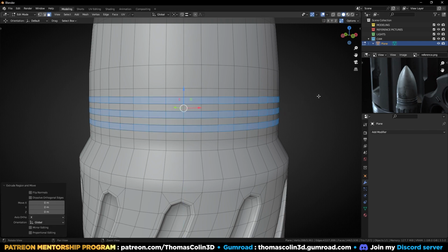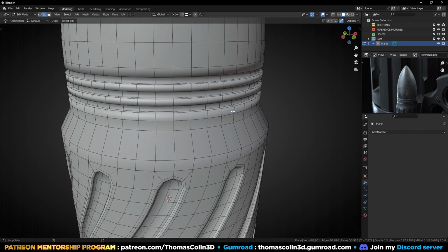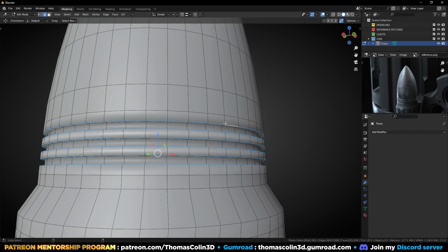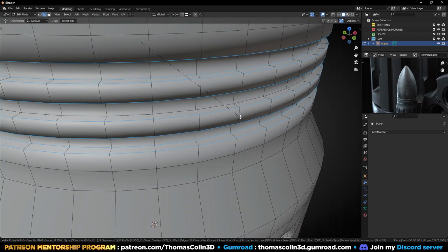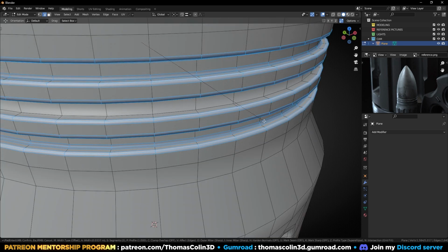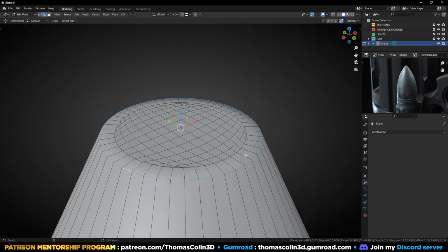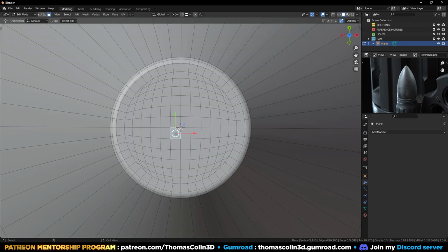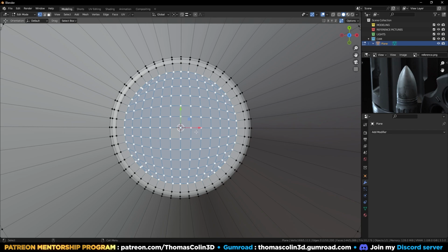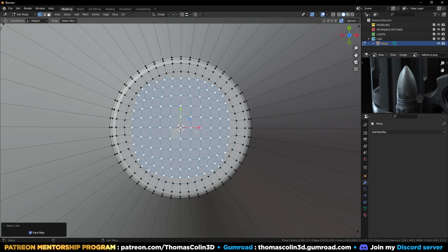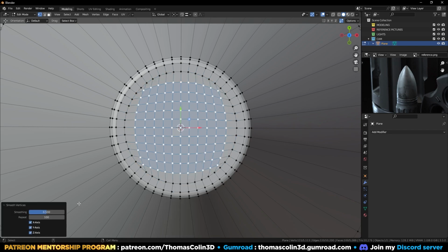E, right click, Alt S, select the sharp edges, Ctrl B to bevel with 1 segment, P to set the shape to 1, select this edge loop as well, Ctrl B, select one face, Shift G to open the Select Similar menu, select Coplanar, press Ctrl minus to shrink the selection, press 1 to change the selection to vertices, shrink one more time, right click, smooth vertices,